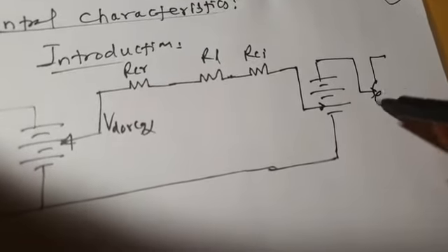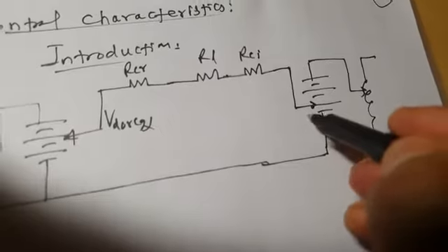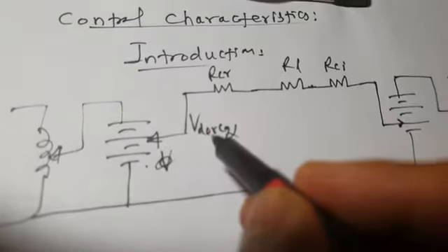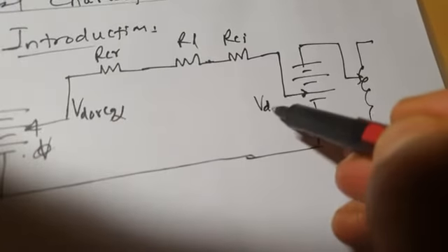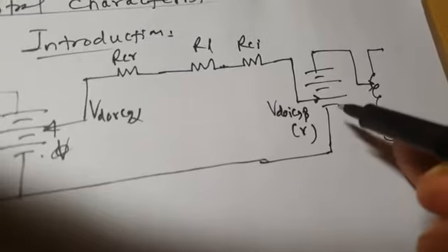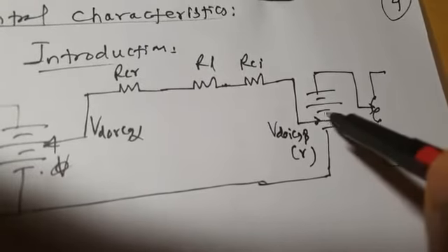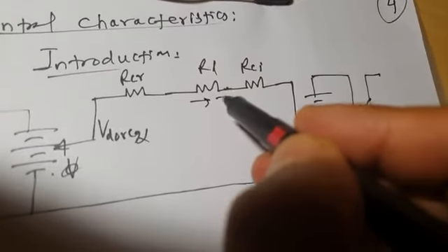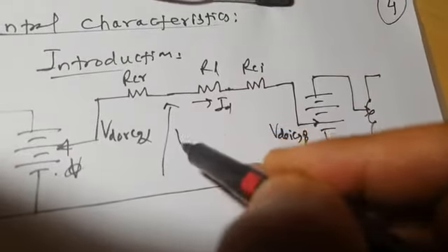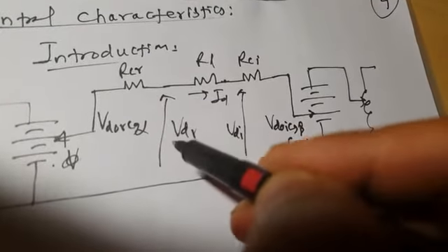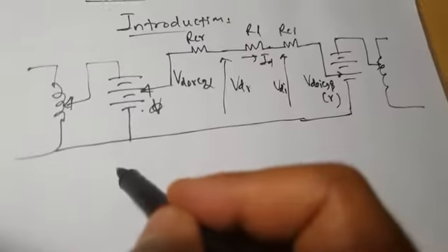And this is the tap changing transformer. What is this voltage? What is this voltage? This voltage is, you have written VDOR cos alpha, and this voltage is VDOI cos beta or cos gamma, depending on whether you are using beta or gamma. Okay, now this is DC line current ID. This voltage is VDR, this voltage is VDI, inverter average output voltage, rectifier average output voltage, and we know that